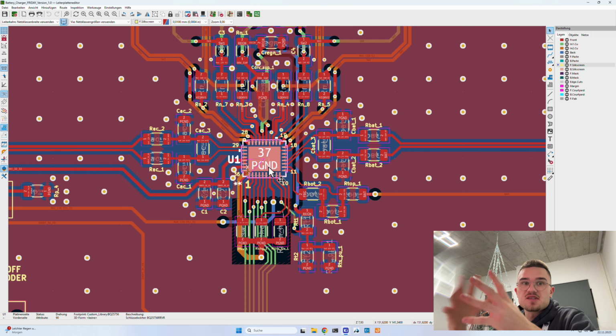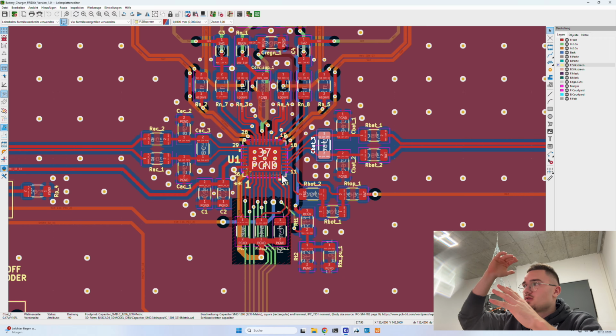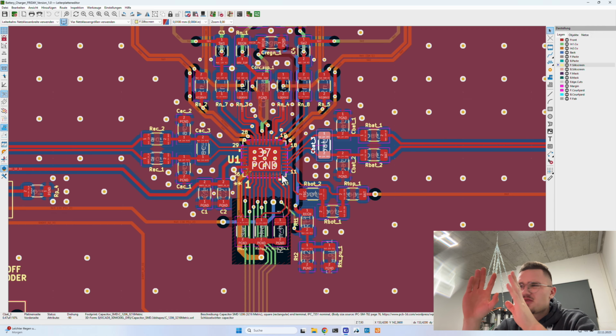worry about distances. So you can't place here, for example, this one here, it's also a capacitor, one of many capacitors. So you can't place them, I don't know, 20 centimeters away. So you can do it, but for the signal it transports, it won't be good. So this is just one of many things you need to worry about when you make the design. But this is also stated in the data sheet of the chips. So there are guidelines. So hey, don't place this component too far away, etc., etc.